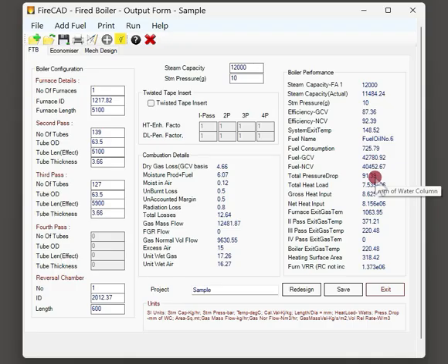So if you consider burner draft loss of 150 mm and duct and other miscellaneous losses as 50 mm, so you can add around 200 mm and around 50 mm margin. So FD fan head should be around 350 mm, something like that. This is the total heat load of the boiler.